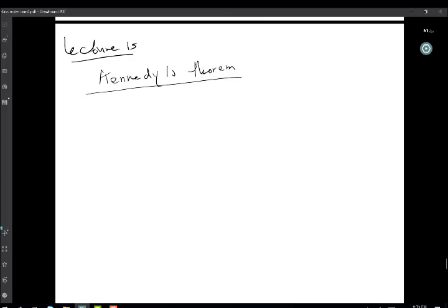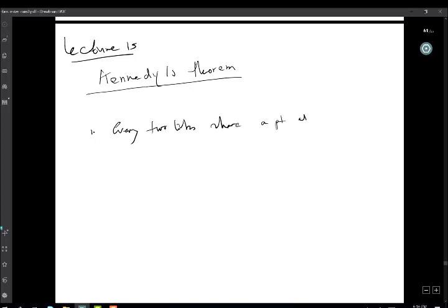Kennedy's theorem says first, item one: in a linkage, every two links share a point of common velocity. And that's, well, obvious, like in a four-bar chain, such as this one here.